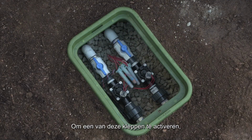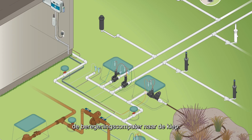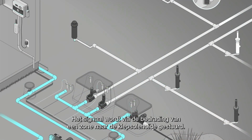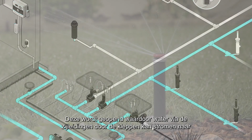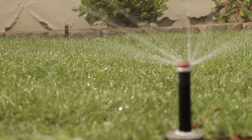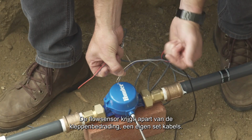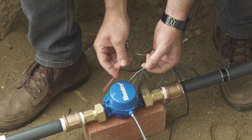To activate any of these valves, a 24-volt alternating current electrical signal is sent to the valve from the irrigation controller. The signal is sent through a set of station control wires to open the valve solenoid, which allows water to flow through the valves, through the lateral lines, and then to the sprinklers or irrigation devices. The flow sensor, or flow meter, will receive its own set of wires separate from the valve wires.